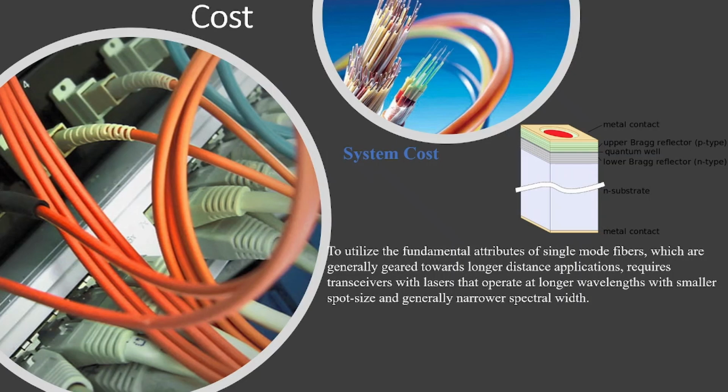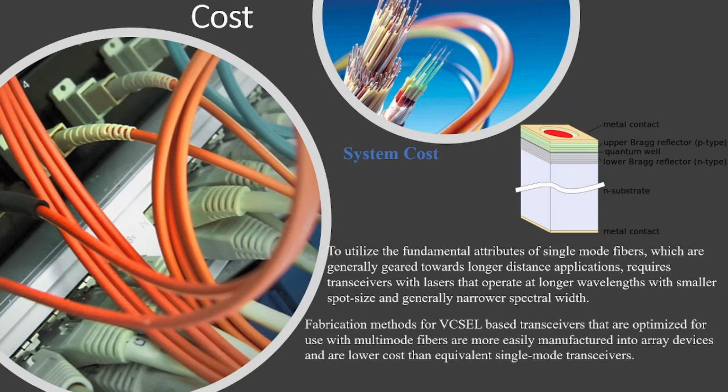These transceiver characteristics, combined with the need for higher precision alignment and tighter connector tolerances to smaller core diameters, result in significantly higher transceiver costs and overall higher interconnect costs for single mode fiber interconnects. Fabrication methods for VCSEL based transceivers that are optimized for use with multimode fibers are more easily manufactured into array devices and are lower cost than equivalent single mode transceivers.